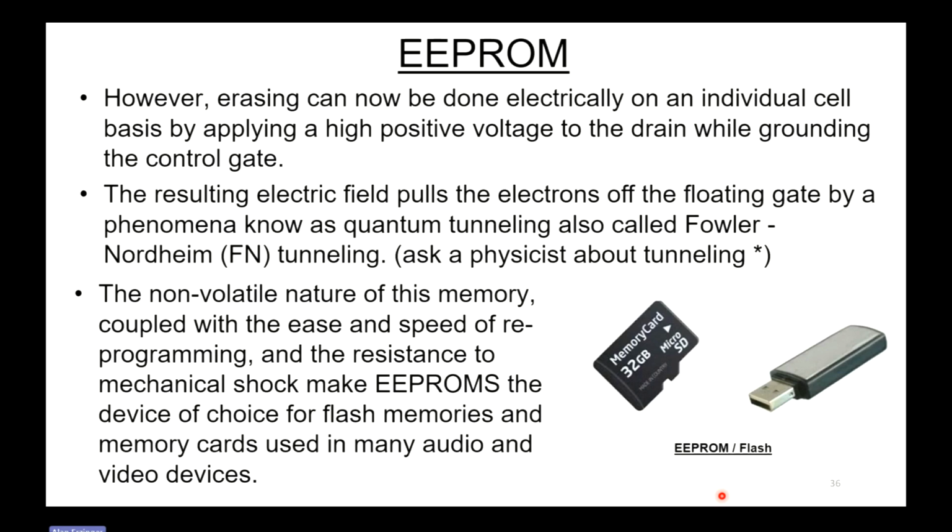The non-volatile nature of this memory, coupled with the ease and speed of reprogramming and the resistance to mechanical shock, makes EEPROM the device of choice for flash memories and memory cards used in many audio and video devices today. All that stuff that you have on your phone is probably stored in EEPROM right now, or an EEPROM structure. It's really a flash, but flash is made using EEPROM and configuring the way the EEPROMs are hooked up.